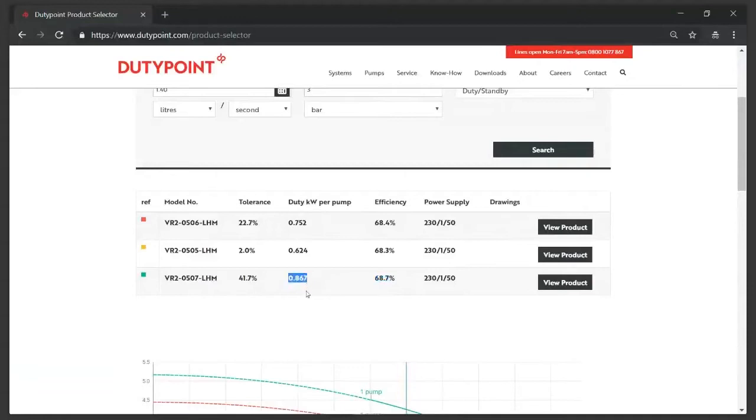So it's worth taking this into account. And yes, variable speed pumping will sort of alleviate that, but still, you can't just rely on the efficiency measure to determine which is the most efficient. Because actually this middle option here is a smaller motor than this third one, and therefore it would actually use less energy to do this particular flow rate that we've asked for.